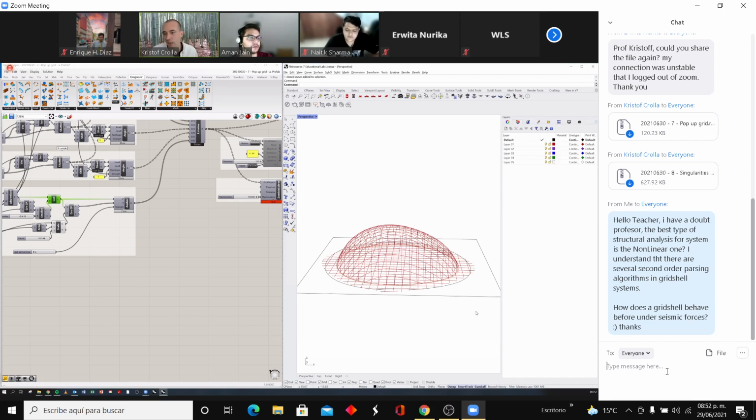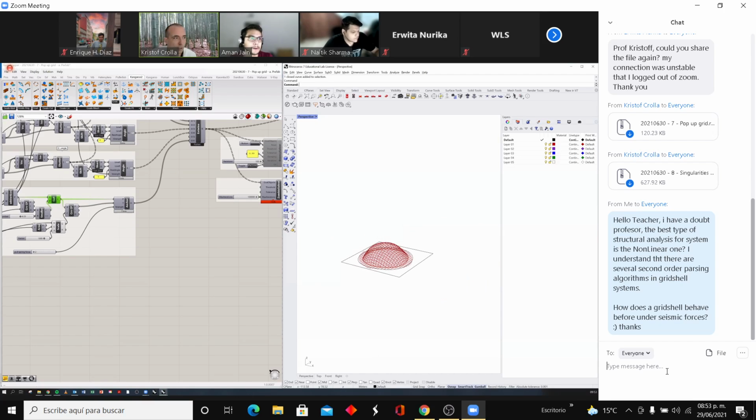I mean, the seismic forces, in principle, behave quite well through it because the system remains in equilibrium, right? It has a setup through the hinges that allow it to move and wiggle around a little bit. So that elasticity of the shell allows it to flexibly, elastically adapt to whatever load conditions you have. It changes the minute you put a high tension fabric on it that is tailor made, because that locks the mesh and all the diagonals into place as well. That incredibly stiffens the structure. And also the diagonals that you would add to it stiffen the structure. Which actually brings me to the next exercise, how to put the diagonals in it.